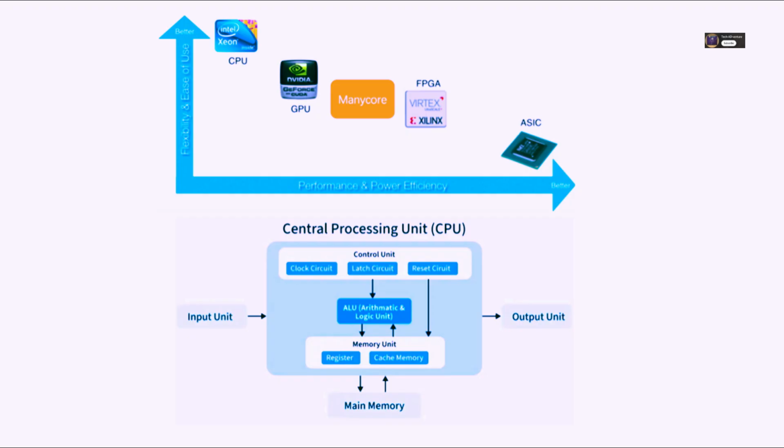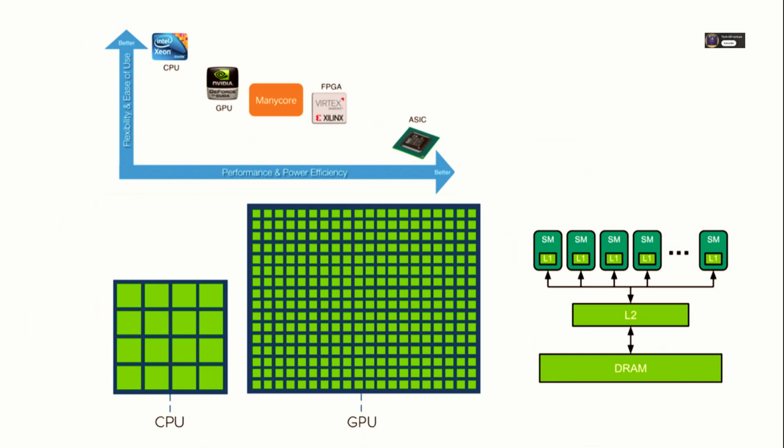Okay. And then we swing completely the other way to the GPU, the graphics processing unit, which has totally transformed AI and data processing. Totally. The GPU is a parallel powerhouse. So instead of having a few very complex cores for sequential tasks, it's got thousands of smaller, simpler cores. Right. And its architecture is designed for SIMD, single instruction, multiple data, which basically means it's amazing at highly repetitive data-parallel jobs. Like churning through huge matrix multiplications. Yeah. The kind you need for AI training or complex computer vision.